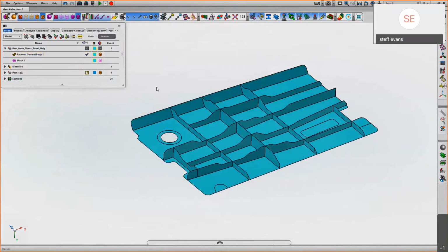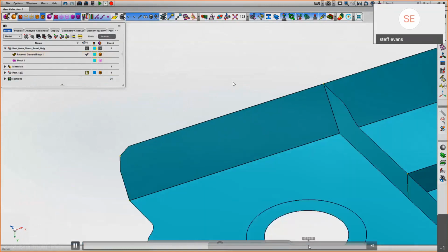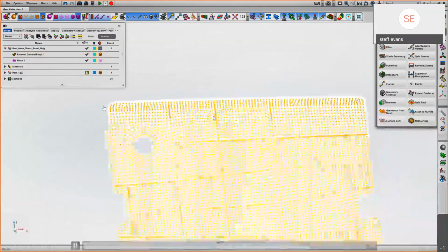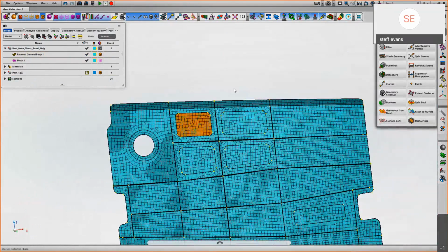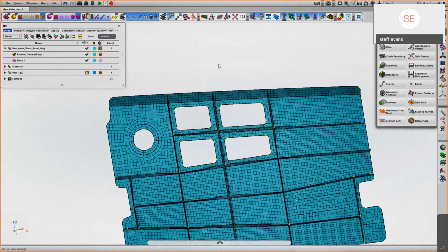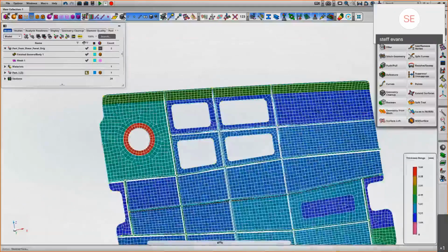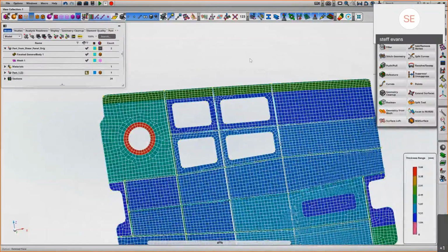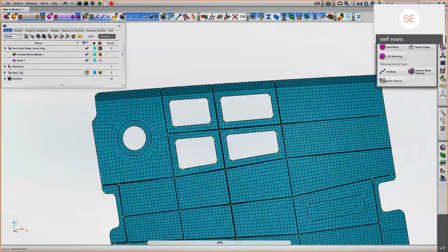Okay, I'm just going to skip on a little bit here, just for time purposes, but you can see here we've actually manipulated those faces from the underlying geometry, and the shell properties have been retained, so we haven't had to revisit the whole of the mid-surfacing and meshing operation. The shell properties have been retained, and we're pretty much good to go.